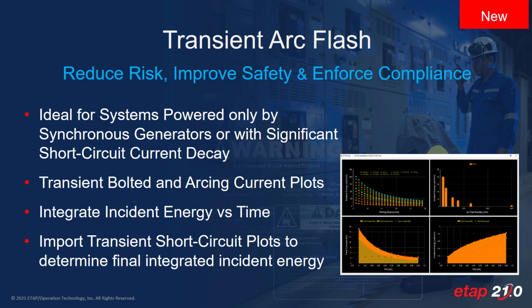The onset of microgrids and DERs make it much more important to have more accurate methods to deal with islanded short circuit sources. This new feature allows the users to specify the time constants and X/R content of the bolted fault current and conservatively includes such effects for systems for which these parameters have significant effect.